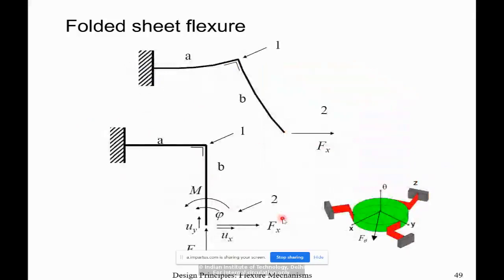And they are used in various applications. One of the things I discussed with you earlier is that you can design a very good planar stage which can give you displacement in x, y, and theta rotation. That is, translation in the x and y directions, and rotation in the z direction. But only motion in a plane, and it's much better than three wire flexures because there is no shortening effect. So general formulation again, just like a cantilever kind of thing.